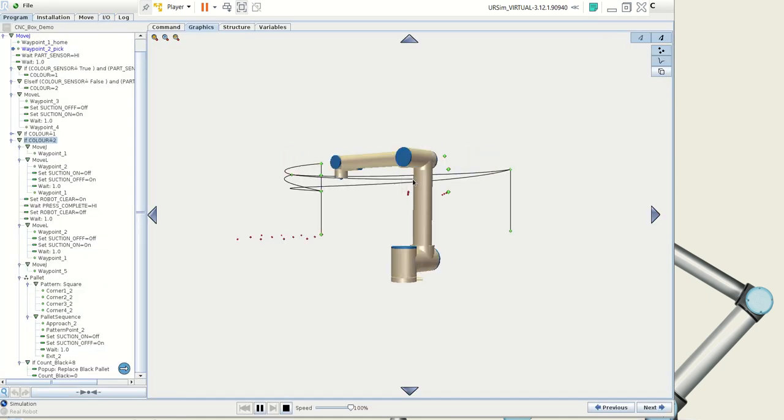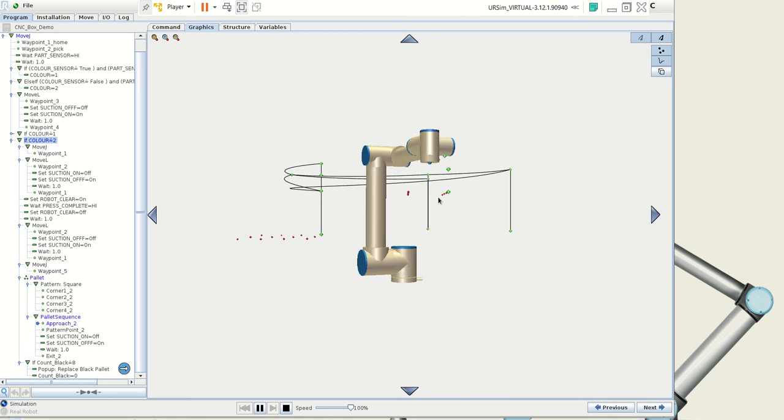And just looking at this, when you're evaluating your performance, you'll see the robot, after it's finished with the black, always comes around here to pick up a part, which probably isn't the most efficient thing. Really, the home position should be just above where it picks up the parts, because that would be the kind of path, or sort of least distance path, I suppose, for both stations to get back to. Because you'll see after this palletizes, drops a part in, it has to swing all the way around to here.